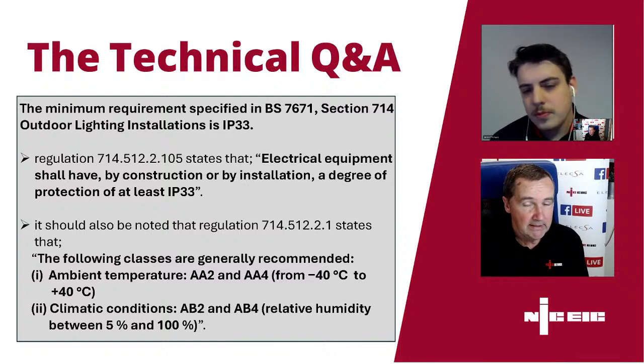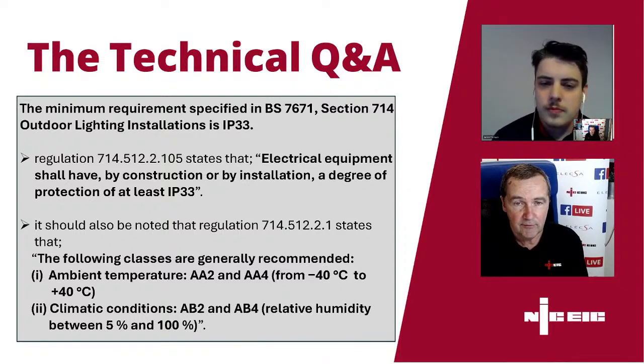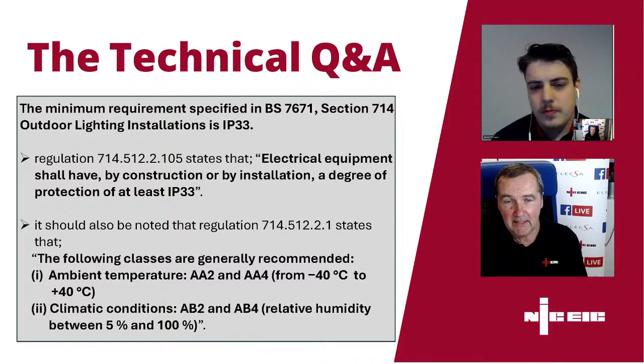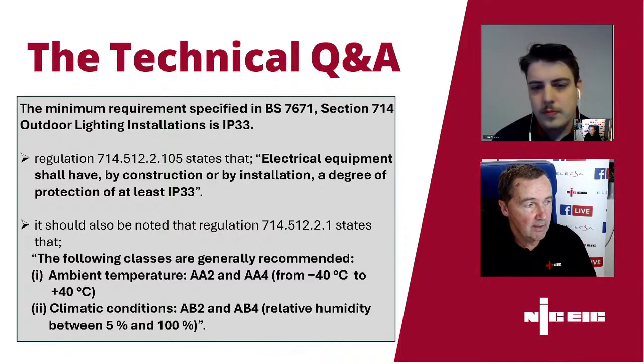So long as it doesn't cause you a problem, so it doesn't increase that much so that none of your overcurrent protective devices work, and the fact that you've said you've got a full RCBO board will mean that they will definitely be okay, because the maximum Zs for the RCD side of the RCBOs will be much higher than 0.46. We would recommend recording it, because one thing you do want to know is if that continually gets higher.